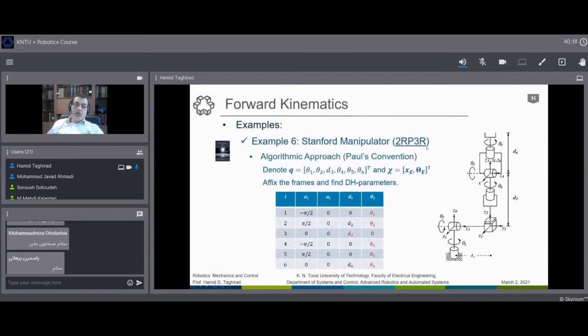We have 5 rotary joints, again a base which is out of plane, then an axis here which gives you the rotation about this axis, but here we have a prismatic joint, and we have a translational motion, and then we have a wrist here, theta 4, theta 5, and theta 6 as before. And as you see, it is also a ZYZ, the direction in terms of Euler angles.